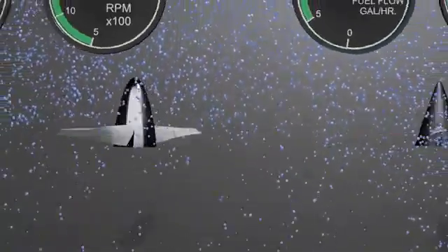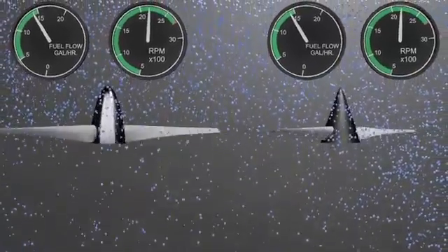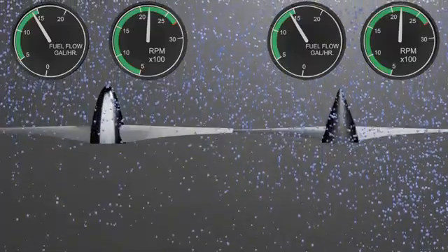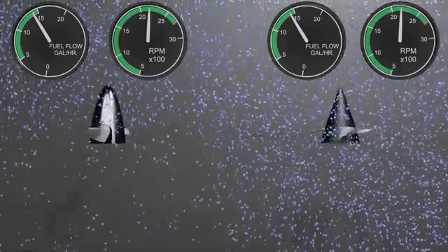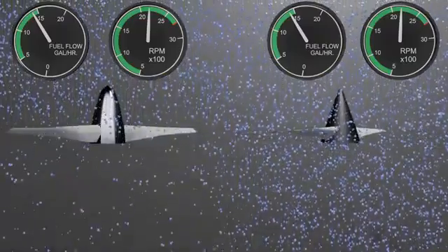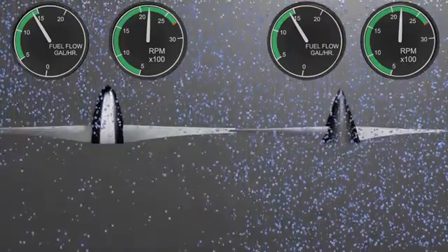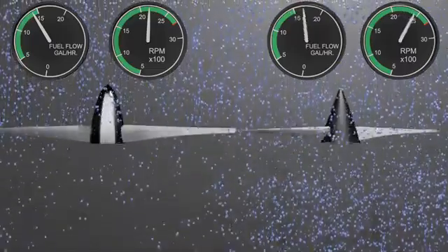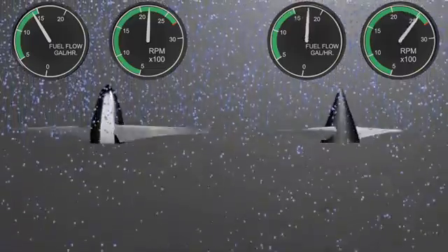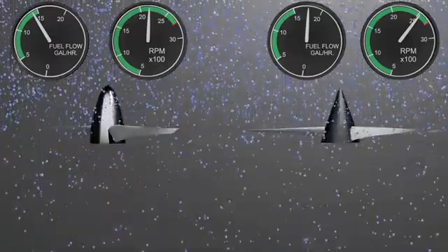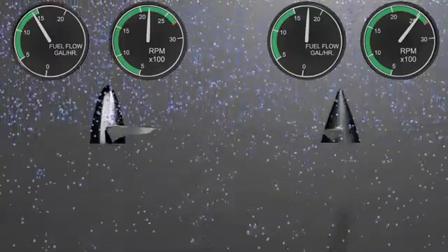So suppose both a fixed pitch and constant speed propeller were at the same speed. Which propeller has blades at a steeper angle of attack? And which one would generate more thrust? The constant speed one. In general, fuel economy is tied to RPM. By maintaining thrust using the lower speed, the constant speed propellers gain their efficiency advantage.